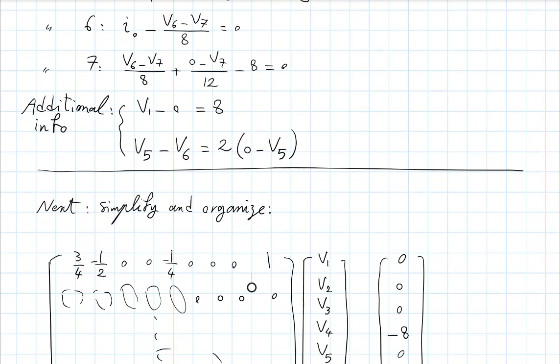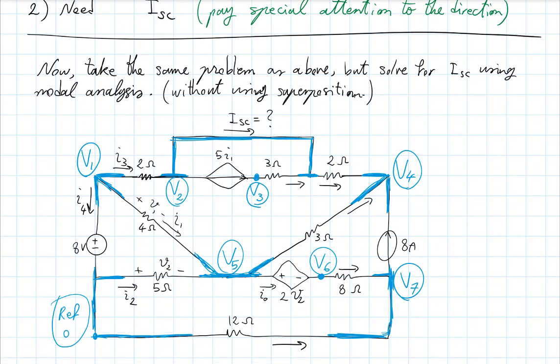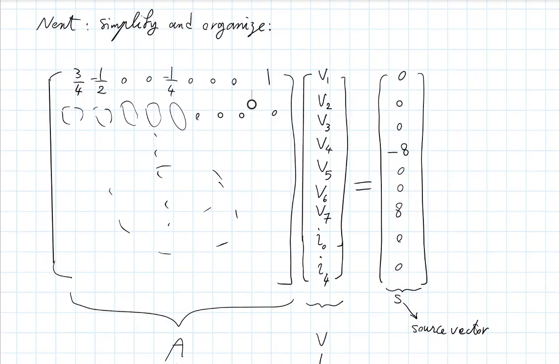So for instance, on the off-diagonal element 1, 2, so row 1, column 2, put the inverse of the resistance that connects node 1 and 2 with a negative sign. So that's kind of a recipe. And you want to be consistent. Again, the equation doesn't change if you add a negative or not, right? So you might as well say, well, no, I choose to have my diagonal elements negative, the other ones positive.